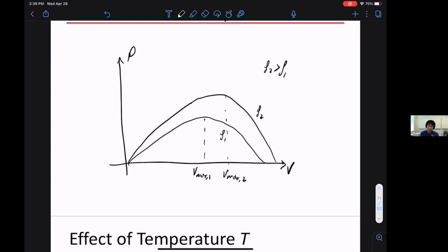So there's a fair bit of electronics around the solar cell that continues to adjust the voltage according to how much current the cell is generating. It's not that you put a cell here, connect two wires to a load, and generate power this way. You have to do some control on the output voltage of the cell.